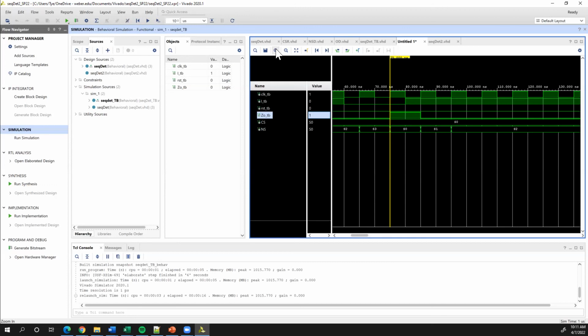Okay. So that's really 3 different ways that you can build state machines, and they are all correct. Well, 4 almost, right? It's use the K-maps, which is awful if we're all honest, right? No one would design a real system this way, but we need to understand it. We need to understand what's happening. The next way is to build each of the blocks separately with those processes, right? And then combinational like I did.